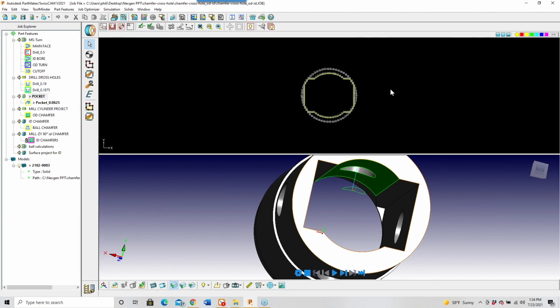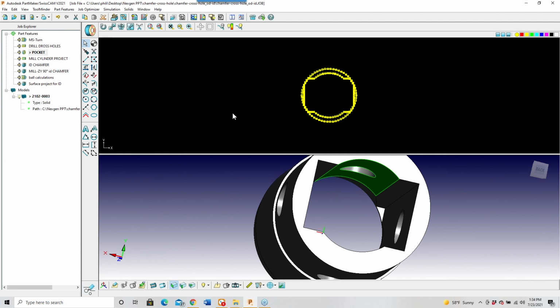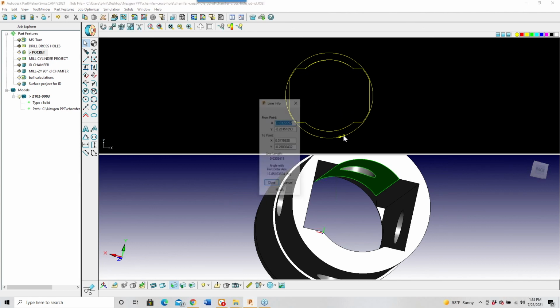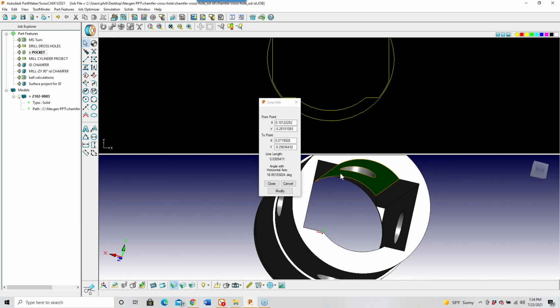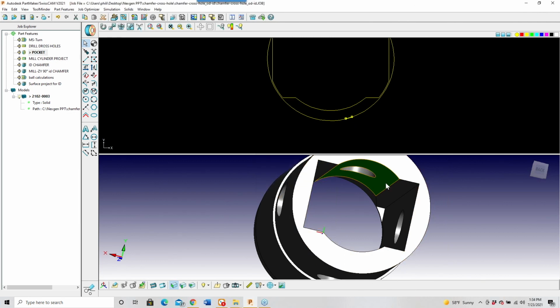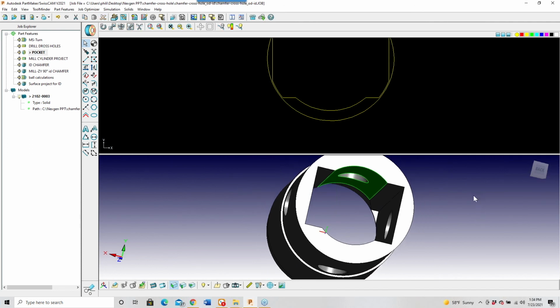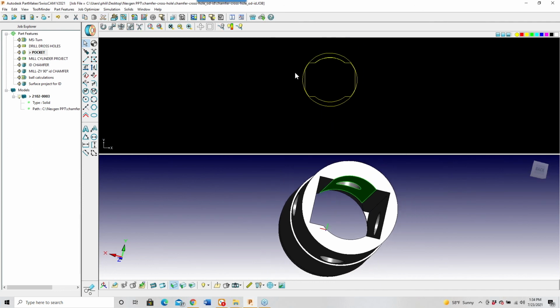So is it better to project as lines than it is to arcs? It depends on the technique you're trying to use. In this case, I would project as lines because I can get really accurate line segments. Now, what does this do? Generates a ton of code because these are little linear segments with G1, G1, G1, G1, G1. But because I'm projecting as lines and making smaller segments, when I select this to project, it'll be more accurate. I gotcha. Okay.